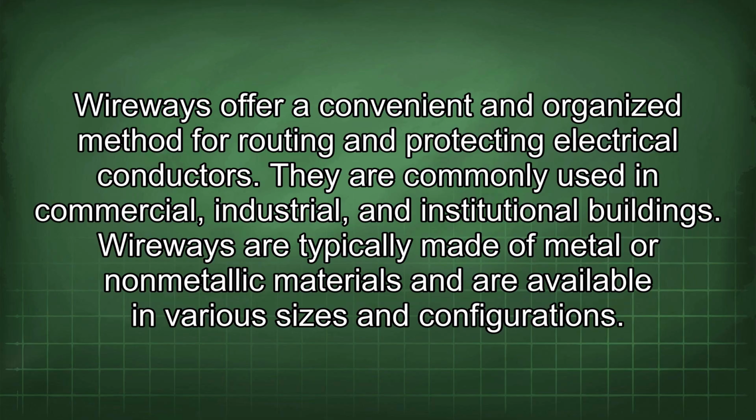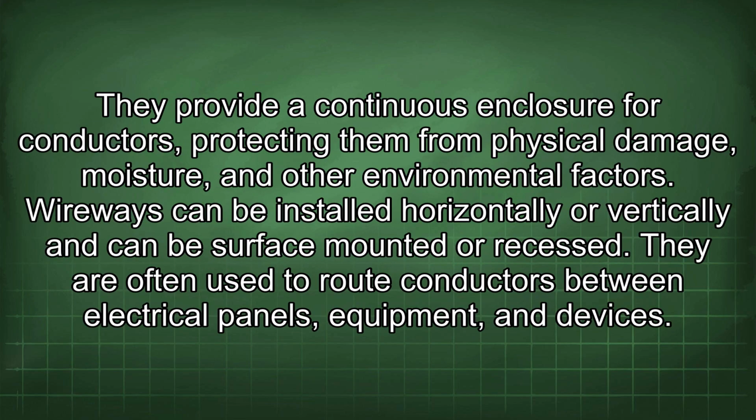Wireways offer a convenient and organized method for routing and protecting electrical conductors. They are commonly used in commercial, industrial, and institutional buildings. Wireways are typically made of metal or non-metallic materials and are available in various sizes and configurations. They provide a continuous enclosure for conductors, protecting them from physical damage, moisture, and other environmental factors. Wireways can be installed horizontally or vertically and can be surface-mounted or recessed. They are often used to route conductors between electrical panels, equipment, and devices.